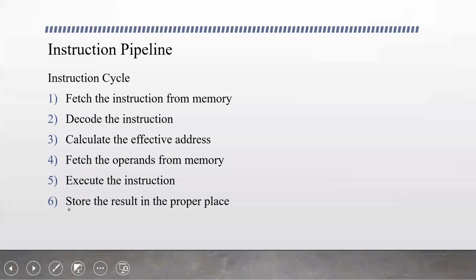And the second type of pipeline, instruction pipeline, allows the instruction to be executed in different phases and parallelly running in different segments. When the decode of the first instruction is carried out, the second instruction can be fetched from memory. This way, parallelly, these different operations that are in different phases can be done in different segments.